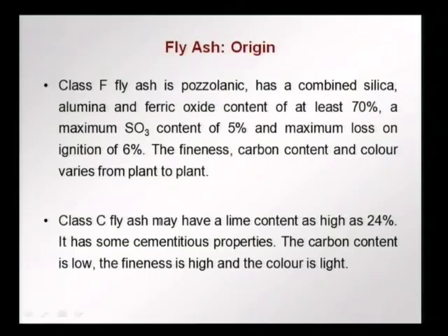There is a lot of variability in this class F fly ash. The fineness, carbon content and color vary from plant to plant. In the case of class C fly ash, there is a high lime content as high as 24%, so it has some cementitious properties like slag. The carbon content is low and generally the fineness is high and the color is light.